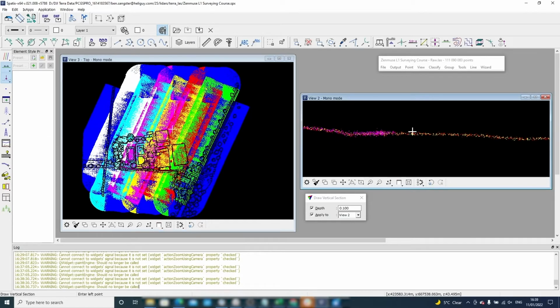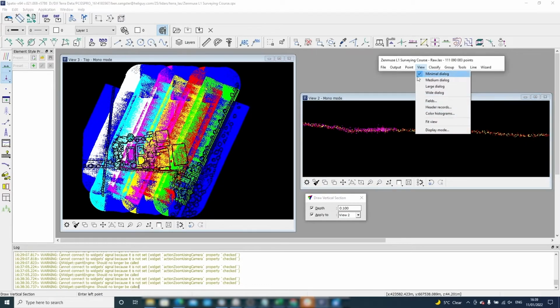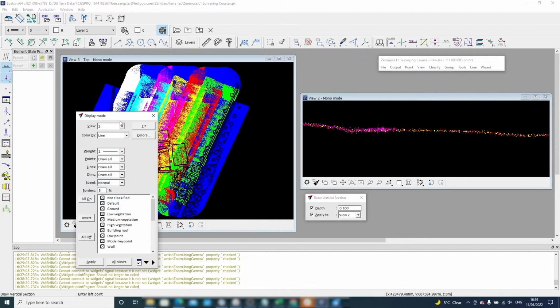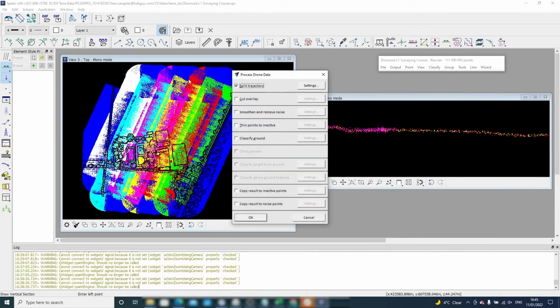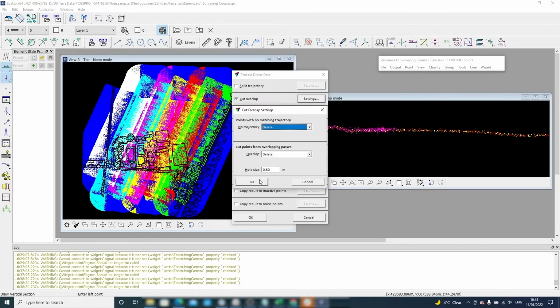If it is not doing so already, using the Display Mode tool, confirm that the new view is being displayed by line. DJI Terra has done the matching for us, and we are using the Spatics platform to verify how well the individual flight passes align with each other. Some passes may exhibit more point-to-point noise than others. The next step of the processing wizard uses the Cut Overlap tool. This keeps only one flight pass at each location, removes the edges of the scan corridor, and removes some of the noise present in the dataset.